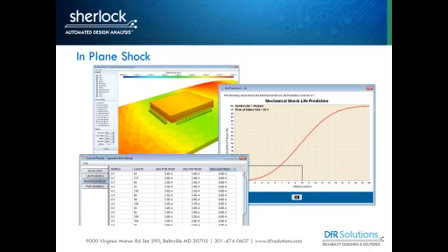So again, as I said before, for large components like electrolytic capacitors that are tall, large ceramic quad flat packs such as this, it may be necessary to go down to the detail of actually modeling the leads so that you know how that part is moving for your expected field environment. And maybe you can't use that type of component in this application because it's just too massive. Or I have to stake that part. I may have to corner bond that part to keep it from moving.